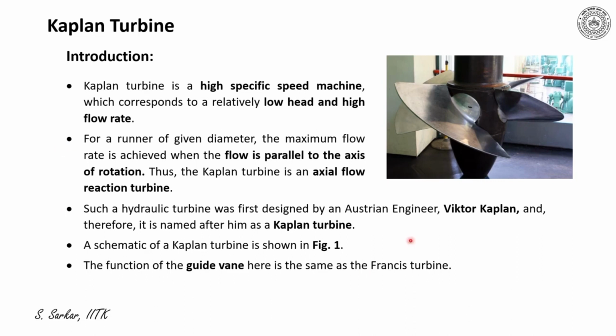diameter. I have indicated here the picture of a real Kaplan turbine, where you can appreciate the turbine having fewer blades, and the blades look like a propeller, very well machined, very well finished rather. And the blades are aerofoil constructions.